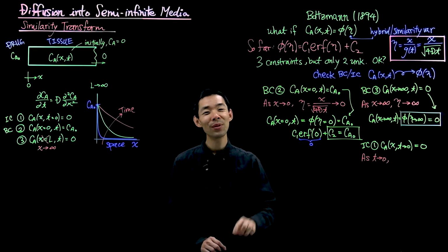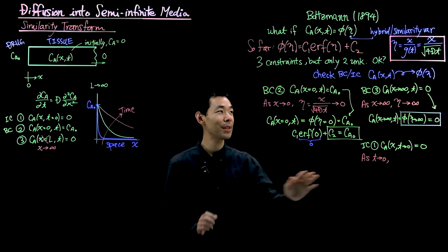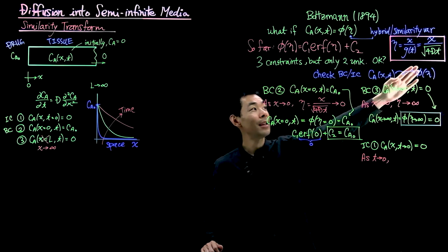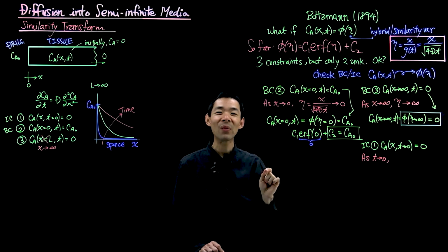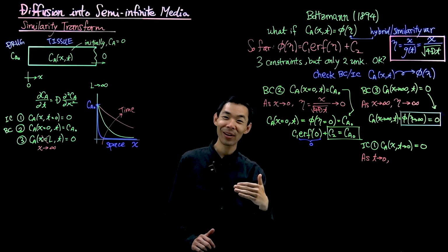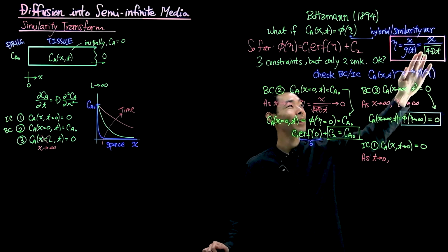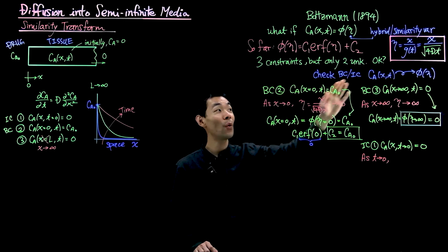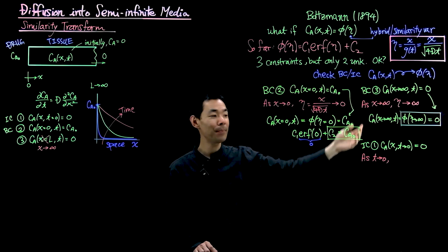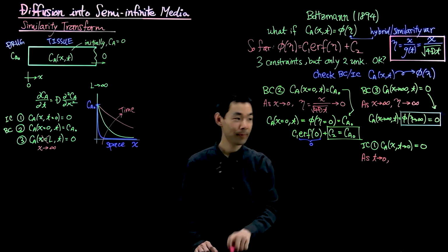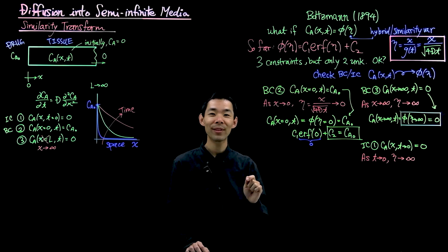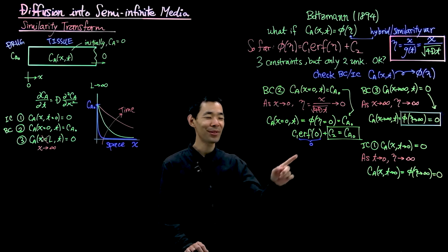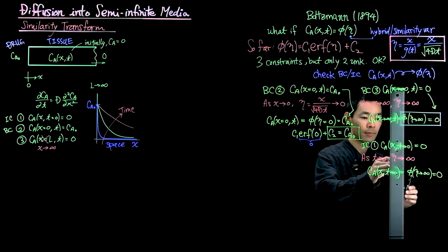As time t goes back to time t equals 0, you can see here that for finite position x, the denominator, square root of 4 Dt, is going closer and closer to 0, and therefore you get 1 divided by 0, which is jetting out to infinity. Therefore, eta is shooting off to infinity as time goes to 0. And therefore, we can convert it over into the phi eta space, just like that. Now, I'm going to circle this one as well, and we can see what happens.